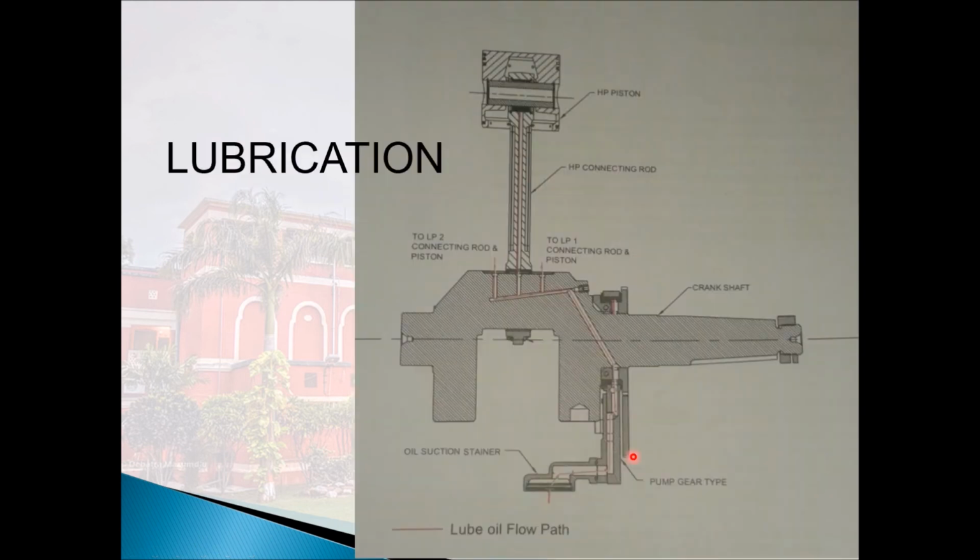The compressor lubricating system is piloted by the gear drive oil pump. The oil pump circulates the oil under pressure. Drive is taken from the crankshaft by means of a set of gears. A primary oil filter, which faces the inner side of the crankcase bottom, filters the oil to prevent the ingress of external agents like dust and other solid particles from entering into the pump and the lubricating system.